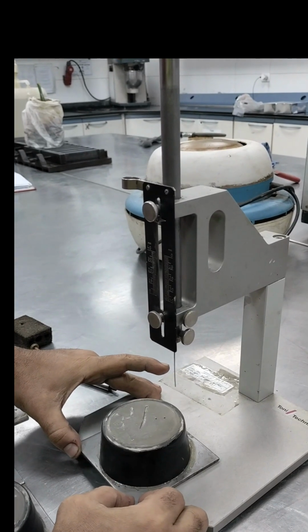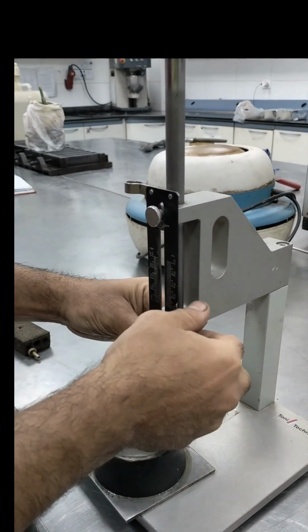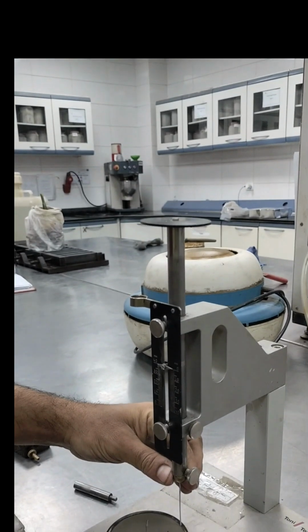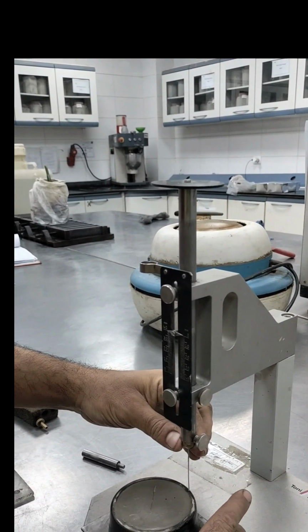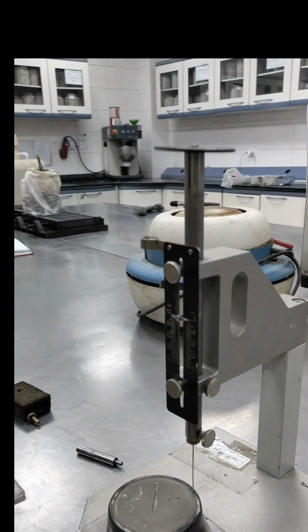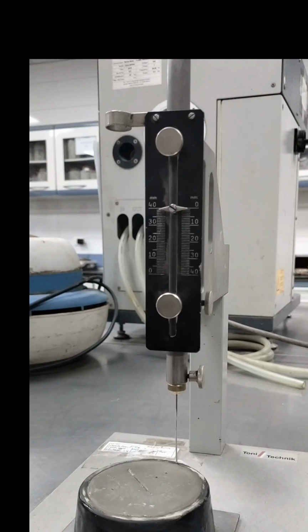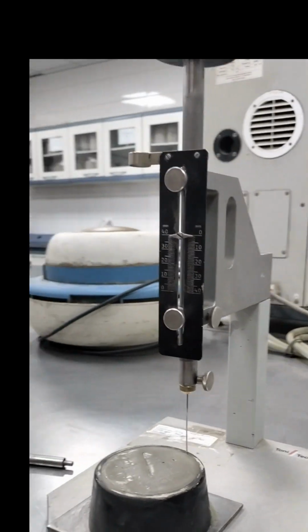Determination of initial setting time. Remove the plunger and replace it by the needle of initial setting. Adjust the Vicat apparatus with the needle attached in advance of the test, by lowering the needle to rest on the base plate to be used, positioned inside the container, and adjusting the pointer or the scale to read 0. Raise the needle to the standby position.